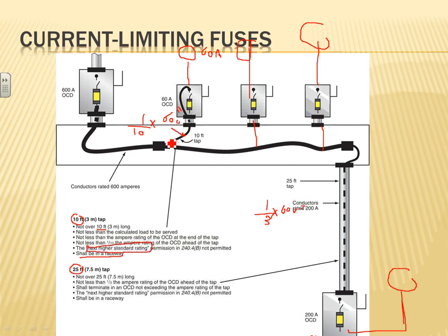So you have a gutter and a big, in this case 600 amp, probably two sets of, I don't know, 300 kcmil going into a gutter, and you're tapping from each one of these phases and going everywhere. What's the disadvantage of it? Survivability of the system. If something happens to this cable here, you lose every single elevator on this feeder. And like Dave said, if it's elevators, you have to do coordination between each and every overcurrent protection device and the main overcurrent protection device.